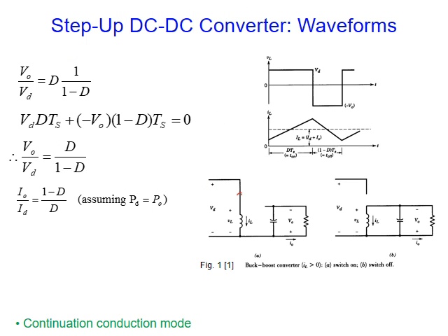When the switch here is on, the diode is off, and you can see a capacitor with the resistance in parallel. When the switch is off, the diode here is on, and the energy is released here. So the current of the inductance comes from the supply and from the releasing of the energy.